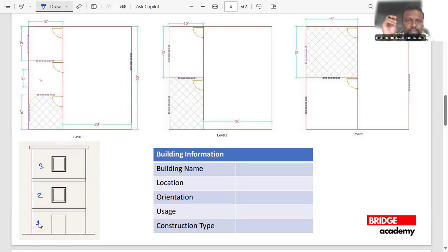Before doing load calculation, in the phase of building survey, you must collect all the floor layouts of your project. For instance, we are doing the load calculation for this whole building. In that scenario, you need to collect schematic diagram and floor layout like this one. Remember, if you are doing load calculation for level 2, let's say this particular room, you need to consider data and floor layout for the floor below. This is level 1, and floor up.